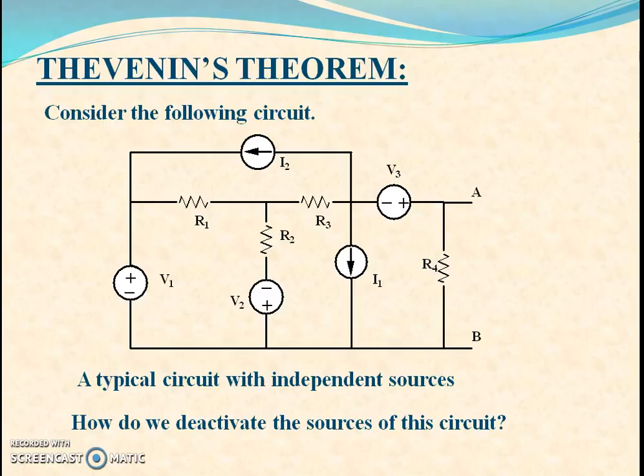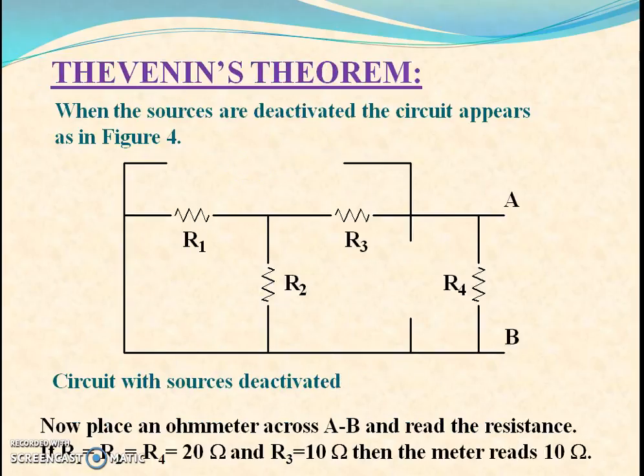That is, we are considering the voltage sources as ideal independent voltage sources, and if we replace the current source by an open circuit, it is as good as replacing it with its internal impedance, that is, infinity, and the ideal voltage source's internal impedance is 0, that is, a short circuit. So how it will look once we do that is this.